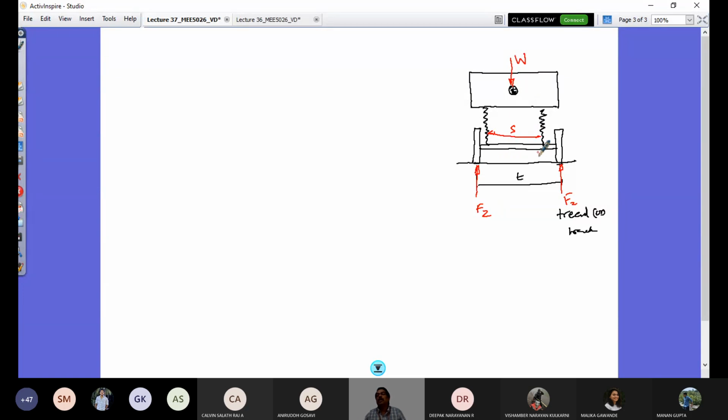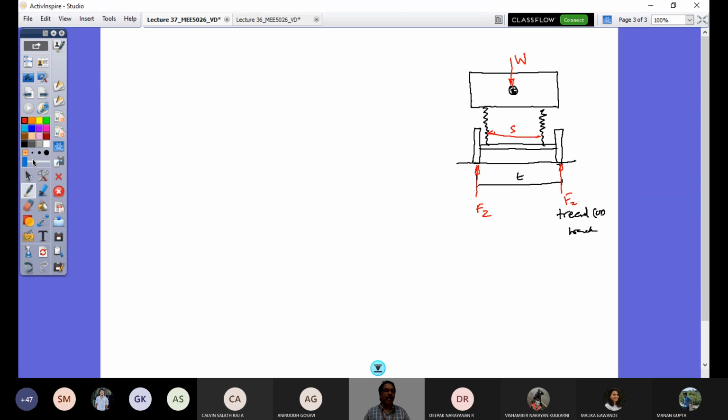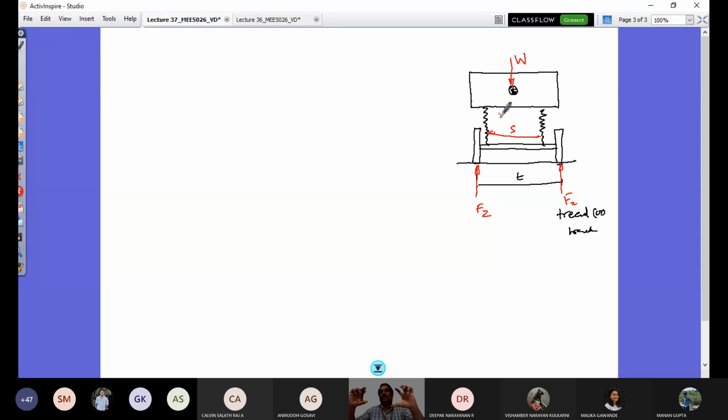So these axles are the front axle and rear axle collapsed together. On each side you can consider the wheels as two wheels together like that, right? So that is the state of the free body diagram if the vehicle goes straight or it is stationary. And the springs are sprung and there will be a static deflection of the spring at that moment.